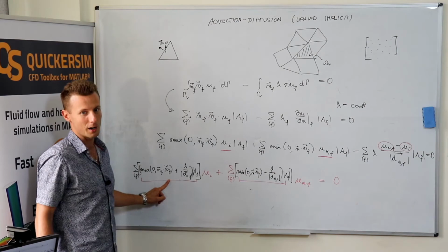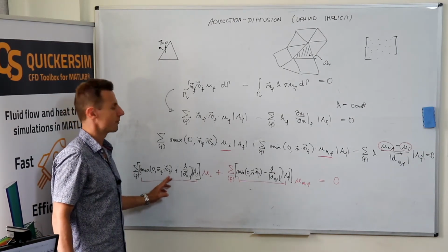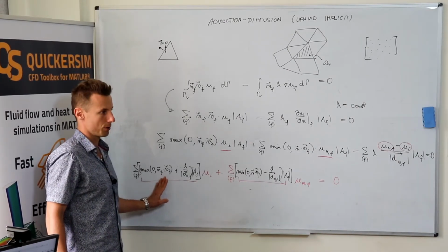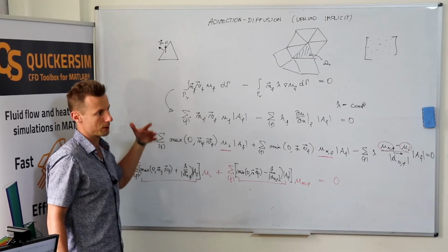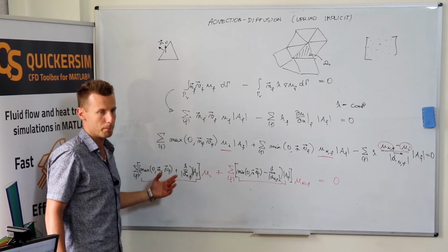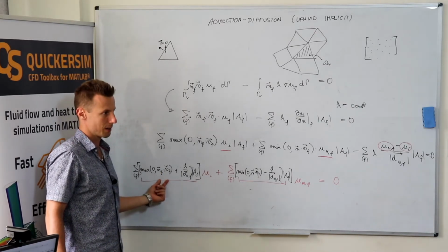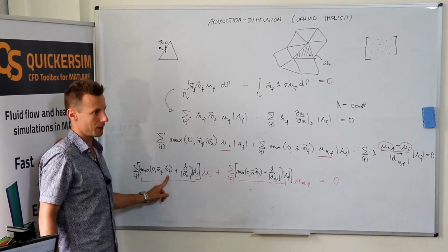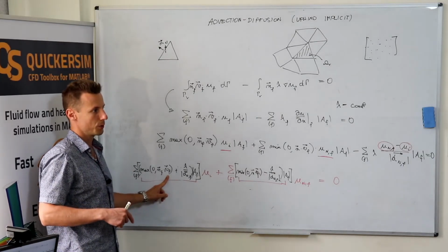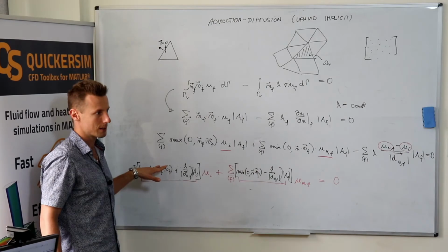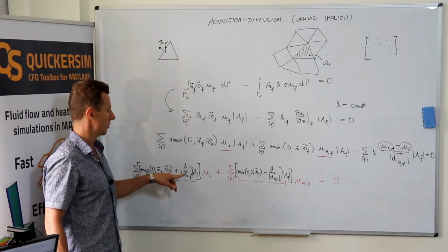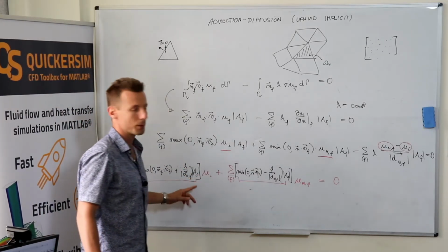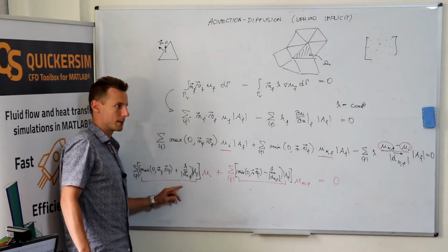Usually, yes. There are a couple of ways. First of all, you need to linearize the problem to come up with constant coefficients that you will be updating from one iteration to the other. There are many ways to linearize the system. Probably the simplest one, and pretty often used, is simply taking the velocities from the previous iteration to calculate the coefficients in the matrix and use these coefficients to solve the problem for the new, well, not necessarily time step because it's a steady state case, but just for the new iteration. It's one of the possibilities.